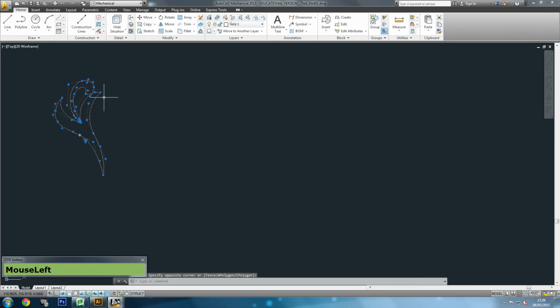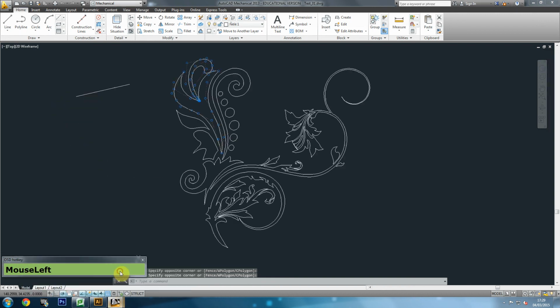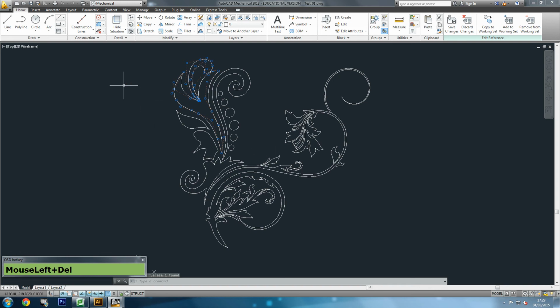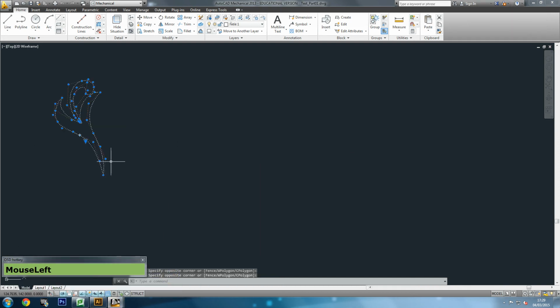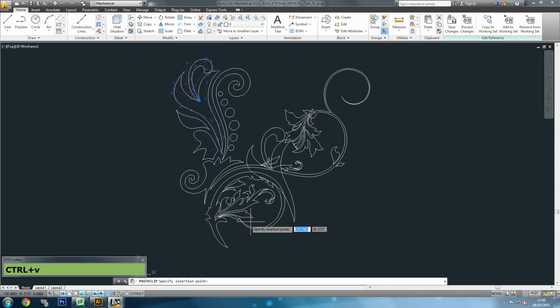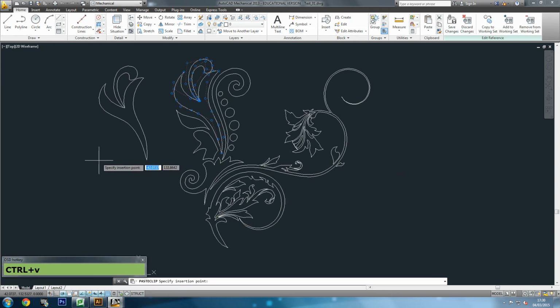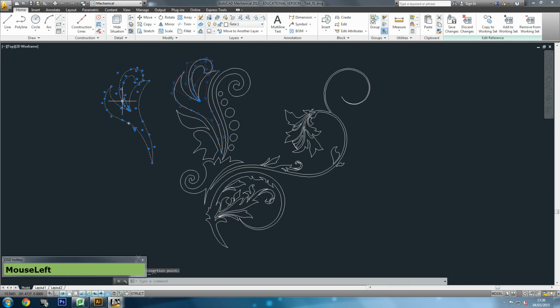And if I did want to take this into the other file, let's say this is my main file, this is where everything is happening, this is where all of my designs are, and I need this additional design to go in there as well. So what I could do, either press Ctrl A to just make a selection, Ctrl A, Ctrl C to copy, go to the other file and just do Ctrl V, and that will paste that design in here, and you could put it anywhere that you like. And this just becomes like any other AutoCAD drawing.